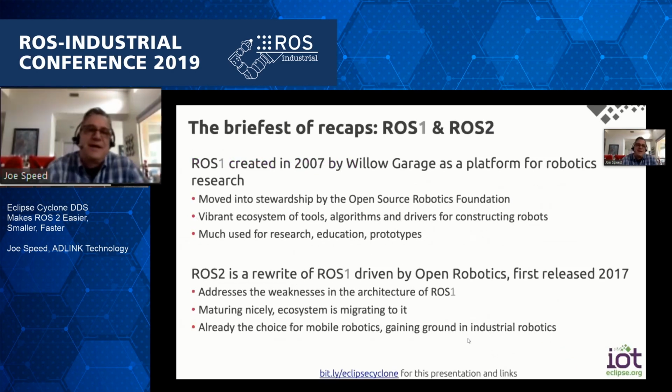So, back to robots. ROS-I, as you all know, came from Willow Garage. It was a platform for research, so it had maybe a bit of a reputation of being developed by academics for academics. With ROS 2, you get a rewrite that's restructured to be middleware based, so that you can begin to get to the things we really care about as you get into commercial use, industrial use, and autonomous vehicles, where you need the robots to be safe and deterministic. So you think real-time, functionally safe, and getting to some of the ISO certifications. Not all of it is there yet, but it's well on the path.